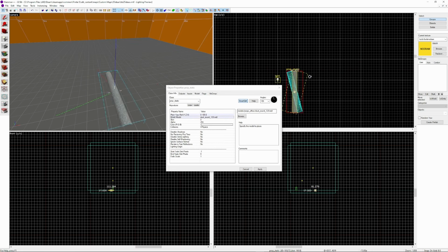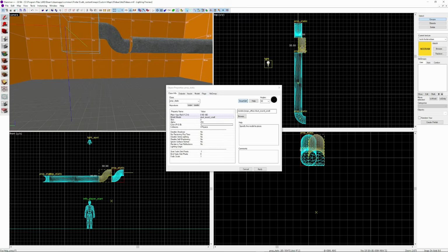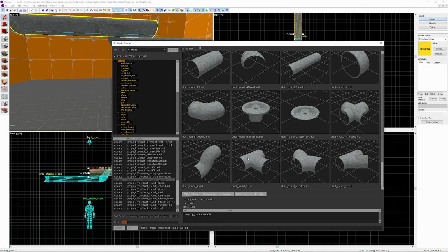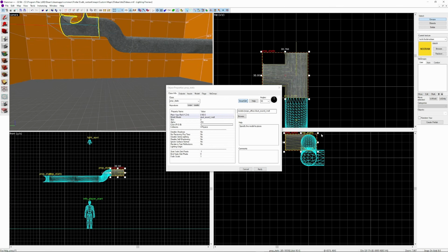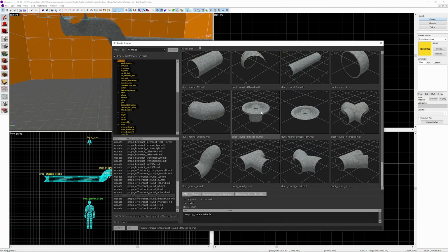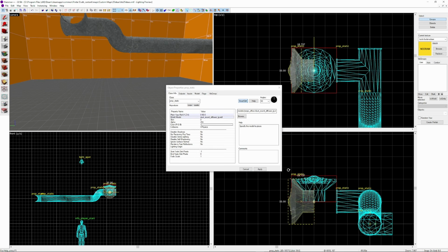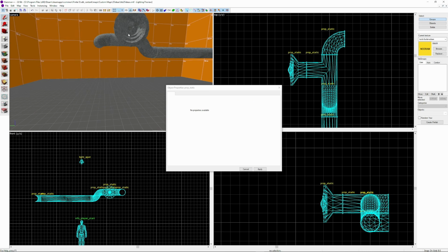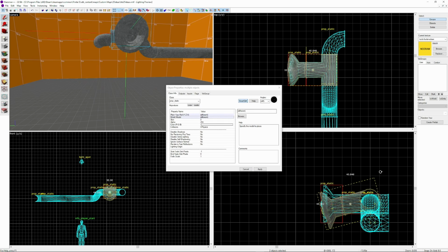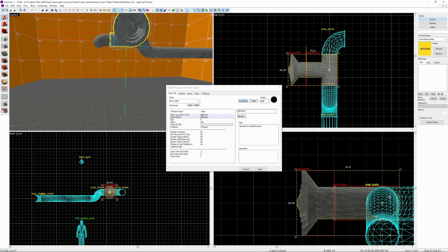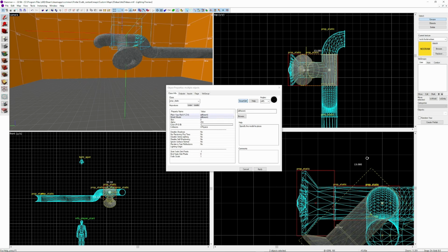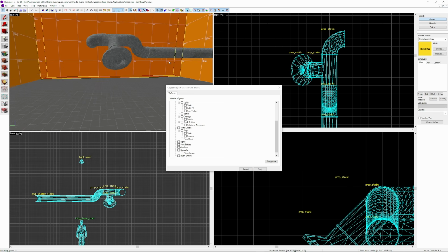Choose the duct round models. I'm using a few different types to create my one. Where you want the bit that shoots out the gas, you want to choose a T-junction duct like this, then create another new duct and make it a diffuser, then connect it to the T-junction duct. Then you select both the T-junction and the diffuser, and then move the origin to inside the main duct part where the T-junction is. You can rotate both of them to face the direction you want.